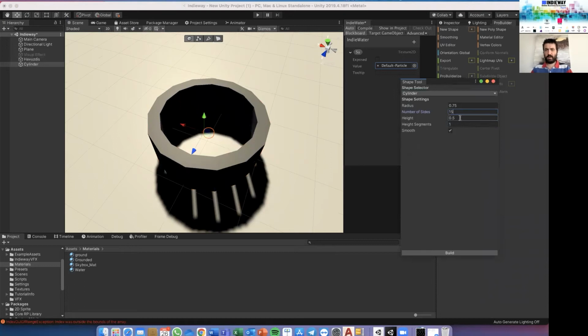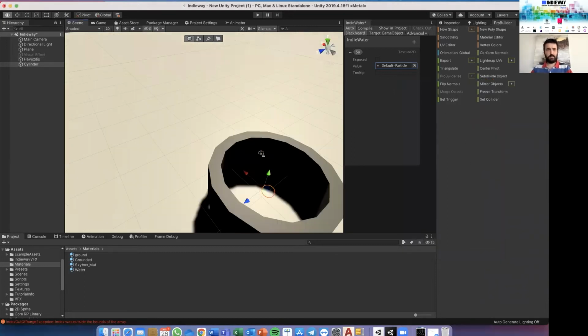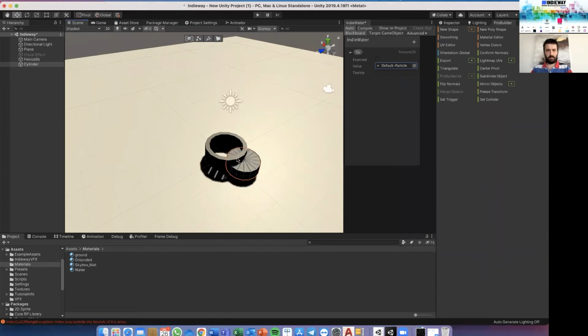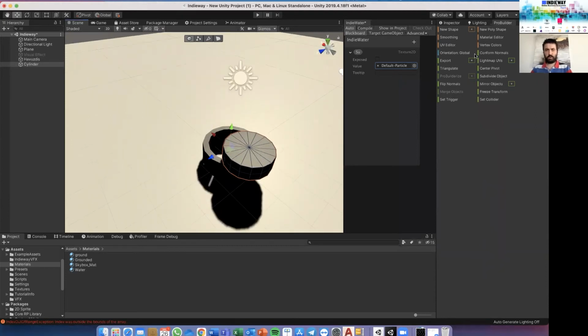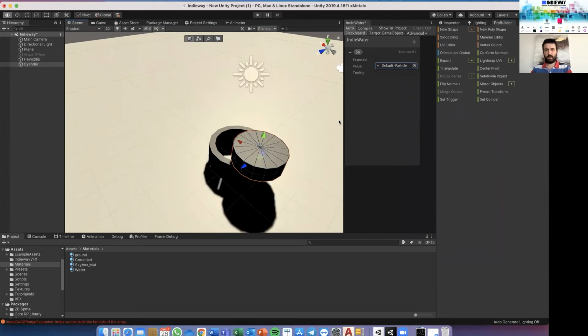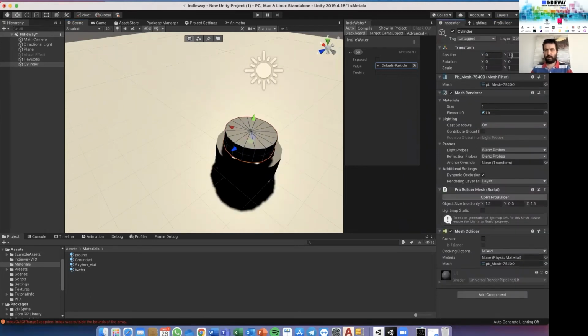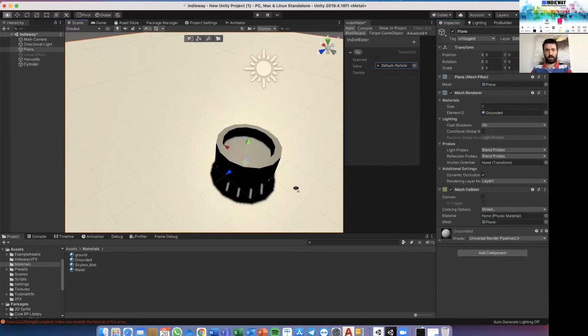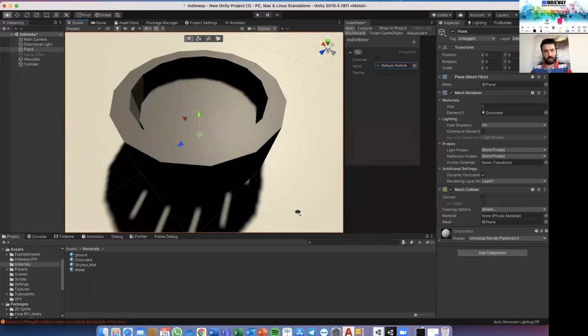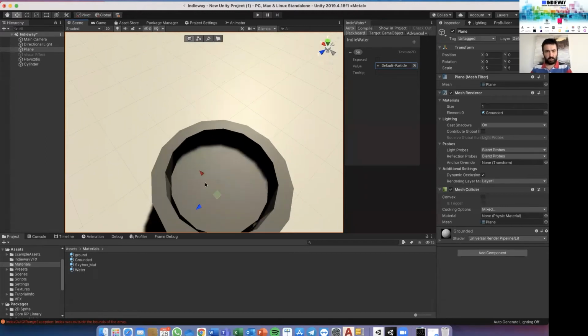There will be 15 arches and its height will be 50 centimeters. And I say build and it will be put upon this. I'm centering it again. I clicked center pivot and again it will be sent to Z 0 and X 0, and in the middle it is settled, and I will expand it a little bit further with the scale tool.